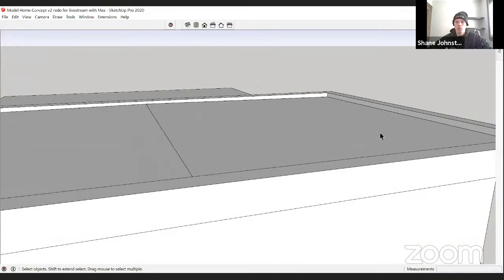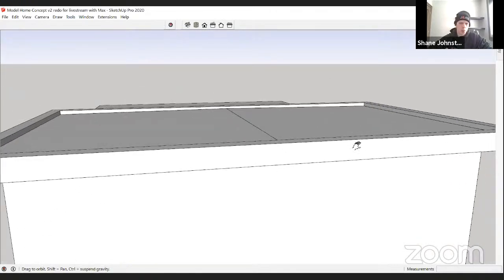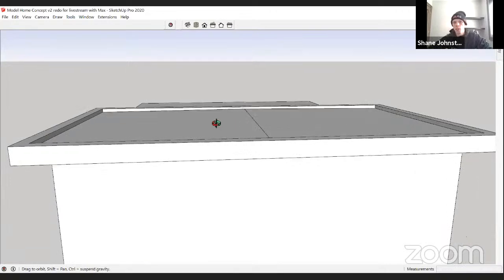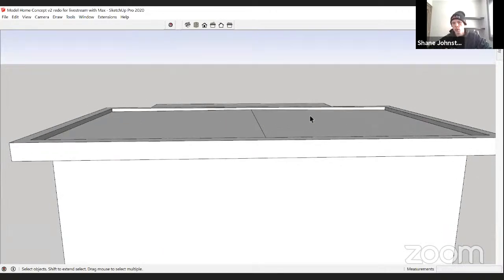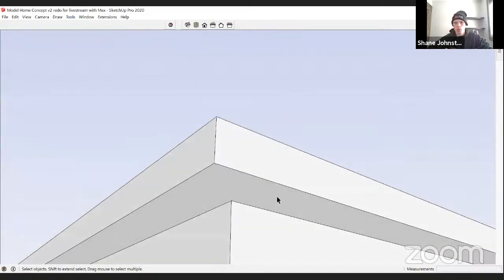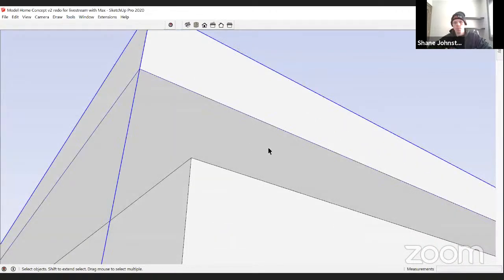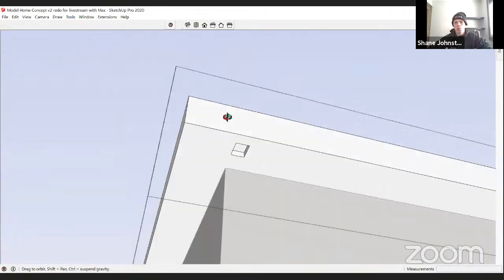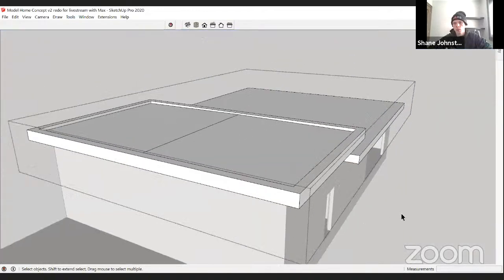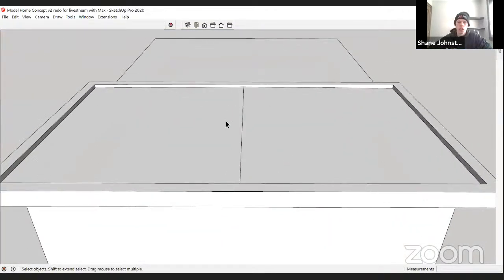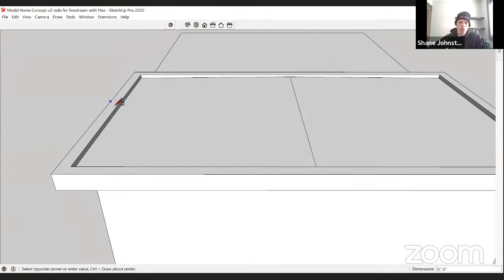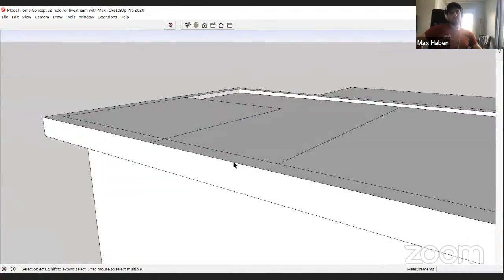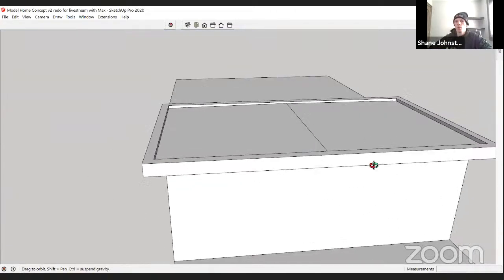So inside the parapet, which I hope that's called, you've got a quarter inch per foot, I think, a little slope, and then those slopes will go down to the gutter box or something, somewhere in there, coming out. So if you build a deck over it, that deck kind of spans like that, and floats over that part. Your drainage still goes down underneath it.